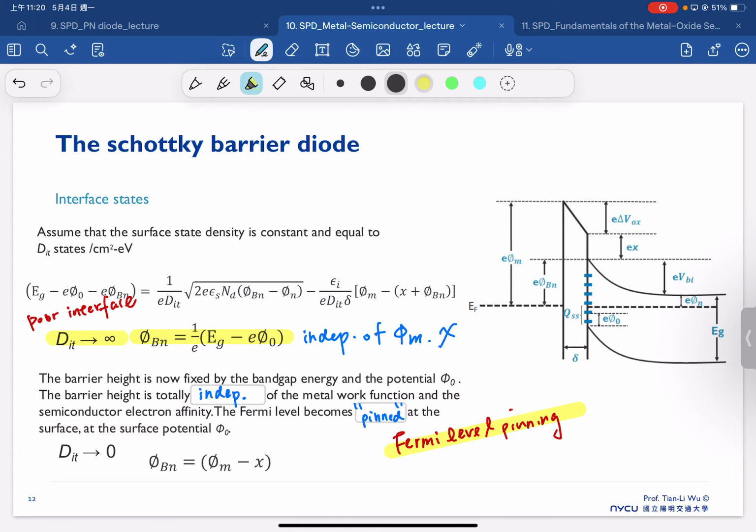So probably this term is new to you if you are new to this field, but you will definitely face this non-ideal effect in the future, because for many advanced semiconductors we always face poor contact, and most of the reason comes from this Fermi level pinning effect, because our interface is way too poor, because we won't use pure silicon.